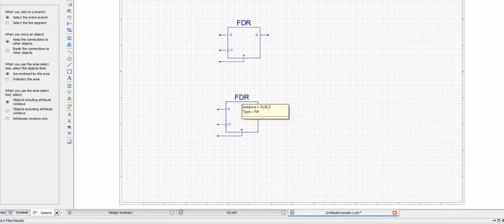We don't want that. We want a system that is reliable and works every time. So we put this reset here. As soon as we turn on the system, it sends a signal to the flip-flops and forces them to be 0, and this way it initializes them. So it is very important that we have this reset here.